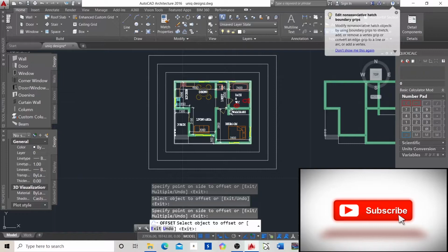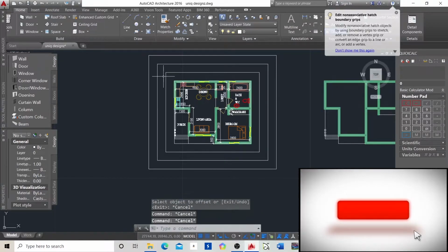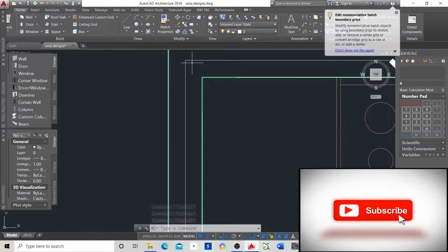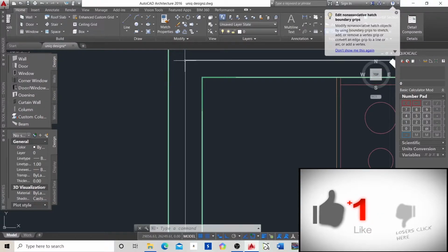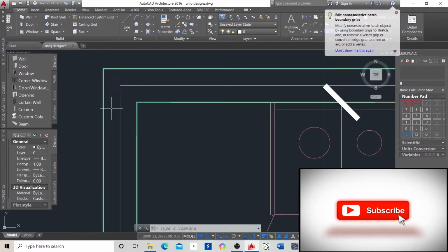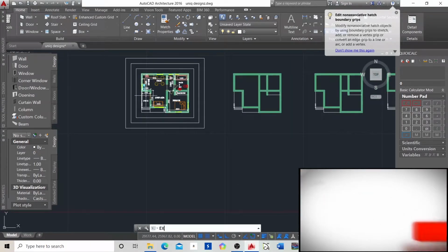You understand? So now you are going to use this one for our grid lines. So let's press escape, and you are going to extend these lines. You understand? You are going to extend this line, because I said we are going to use this line as our what? Grid lines. That's why when you are applying the walls, we couldn't what? Delete it. So you click on extend,